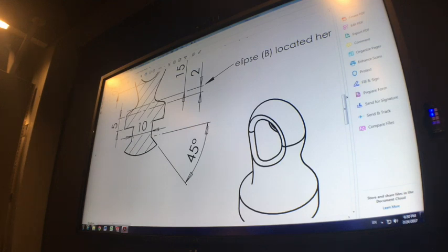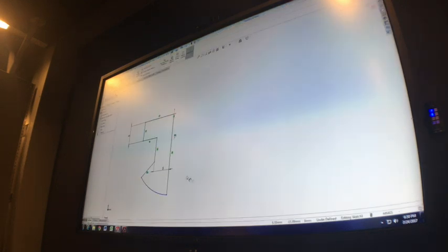I've got a 45-degree angle. So dimension between angled lines, remember, select a vertical or horizontal one. Select the one that's on the angle. And then depending on where you move your cursor, you'll get a different value. So I need to dimension these blue lines that are left.